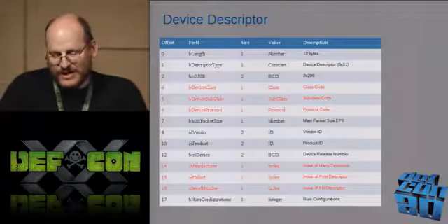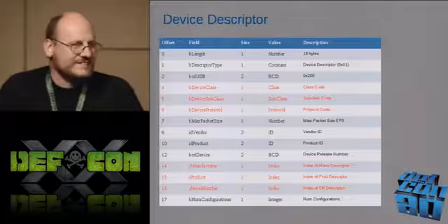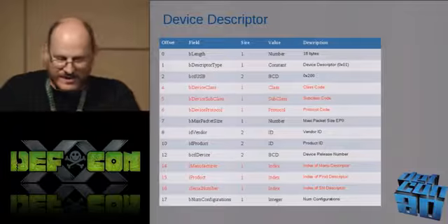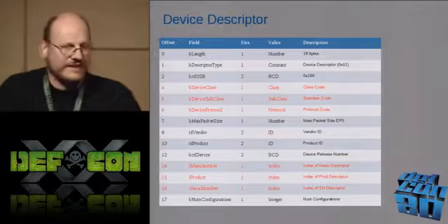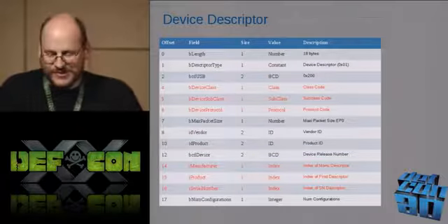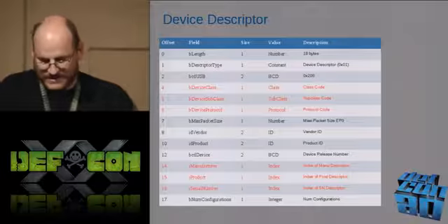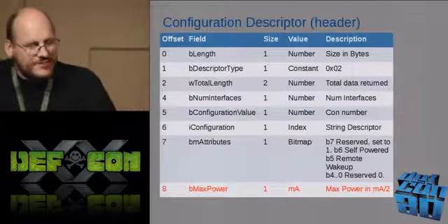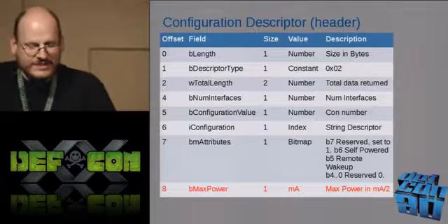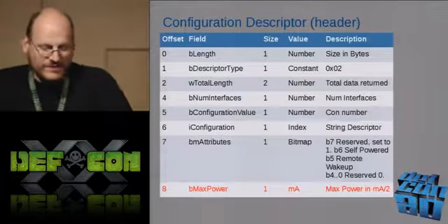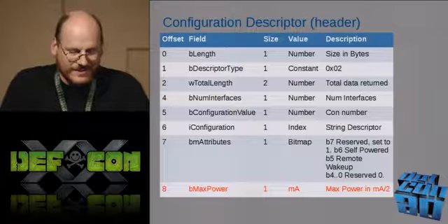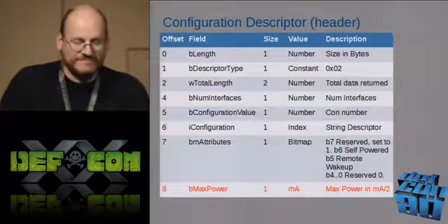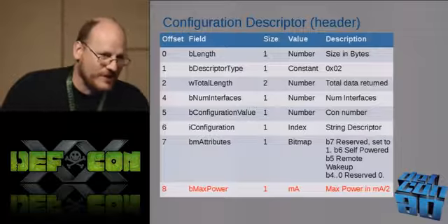And other things like packet sizes. And then we have a manufacturer ID and a product ID. And in some cases, a serial number that has to be filled out. Right? So this configuration descriptor is gotten next. And again, it starts with the length. And then at the type, it's type 2. They're real creative, right? 1, 2, etc.